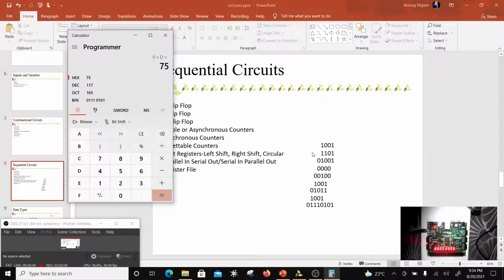So what are you doing? What you are doing is you are taking this number and ANDing it with each digit of B. So let's say this is A, 1001, and then you take B, and each time you are ANDing with a bit of B. Okay, and then you add them, and that generates a carry of 0 here. Okay, next time, whatever is the next number, which is 0, you AND with zeros, so this will be all zeros, and then you add these 4 numbers now, and this one will go to the output.